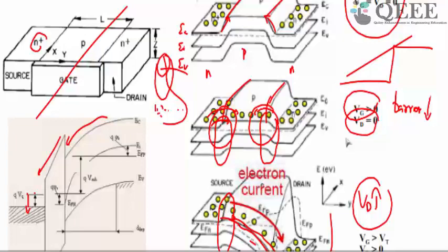So that means that even below threshold voltage, there is some current flowing through the transistor. This comes from the physics of this device only. So there is always injection, but the magnitude of the injection is very small. So at gate voltages lower than threshold voltage also, there is some current flowing through the transistor, and we call that current the subthreshold current.